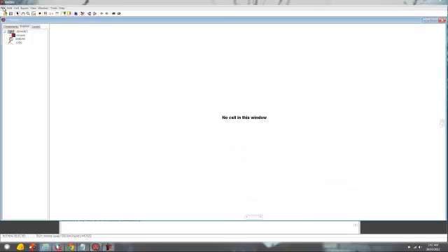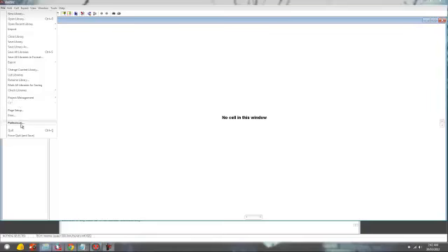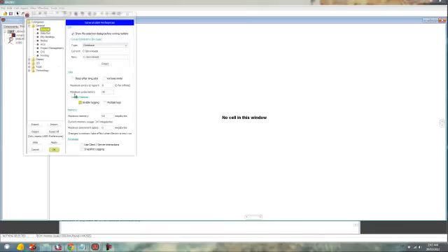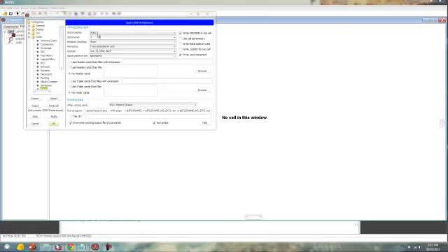So first is the configuration on using LT-SPICE on Electric software. Click on File under Preferences and then go to Tools under SPICE and do this configuration. SPICE 3, level 3. Tick this one and this one. The run program will be the LT-SPICE directory in your computer, and this command will be under the command or in the file. So that's all. Click apply and OK.